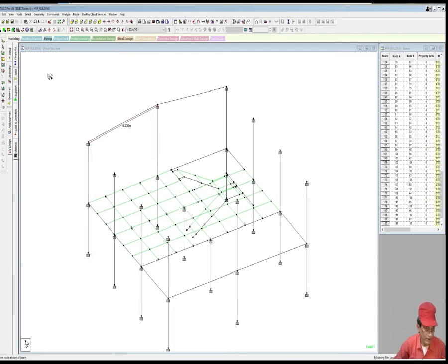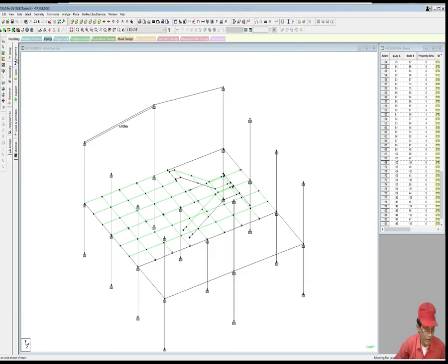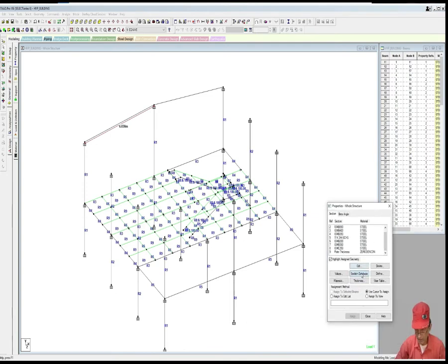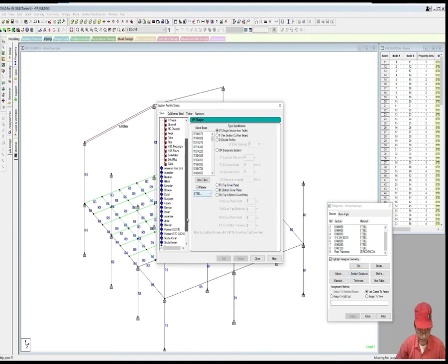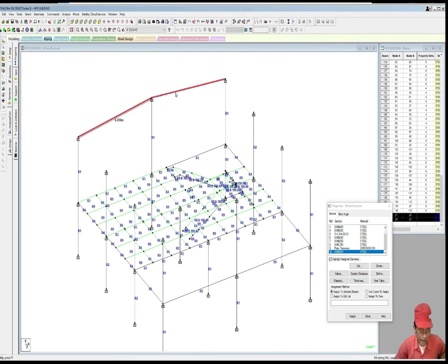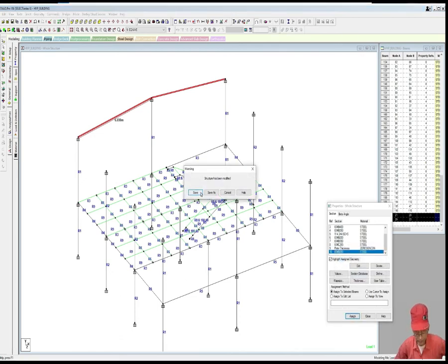So we should assign these, called rafters, as I have already told you in the last sections, or in the section where we planned the framing plan. These members will carry very light load and the span is not much, so let us take Indian ISMB 250, add, assign.